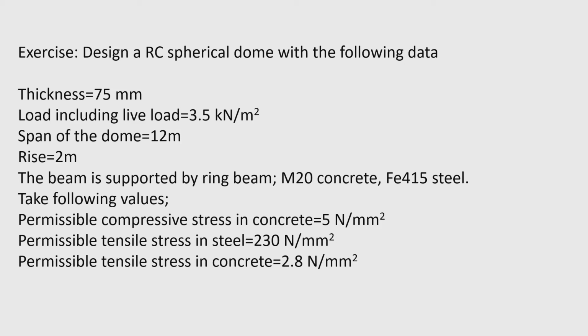Shell concrete also you can take M20 grade, and steel is Fe 415, and also the following inputs are given: permissible compressive stress in concrete is 5 Newton per mm square, permissible tensile stress in steel is 230 Newton per mm square, and permissible tensile stress in concrete is 2.8 Newton per mm square. Okay. Let us see the solution of this problem.